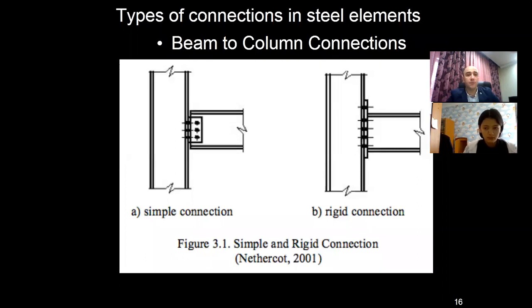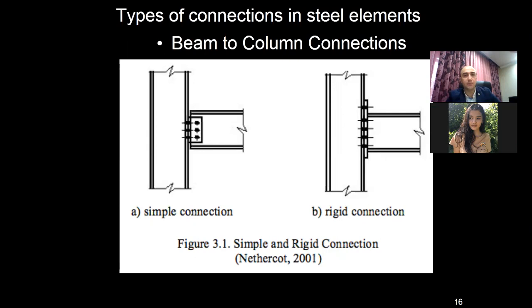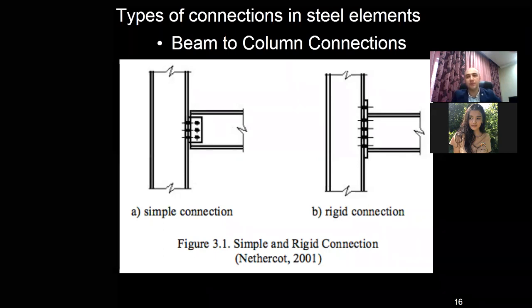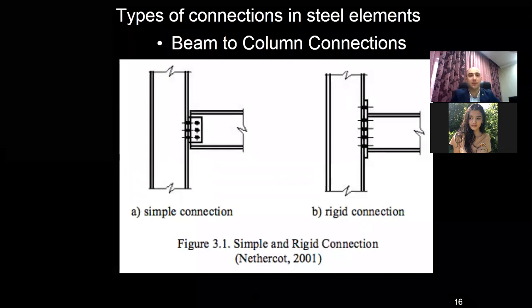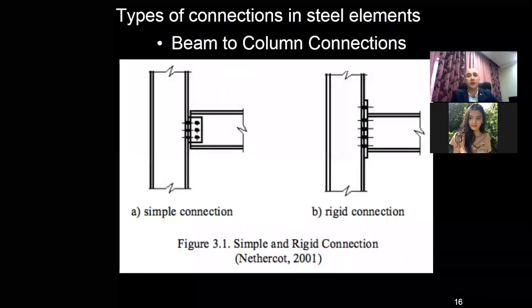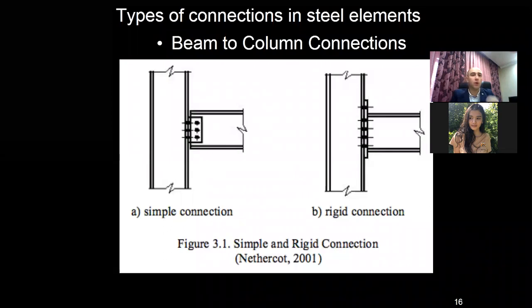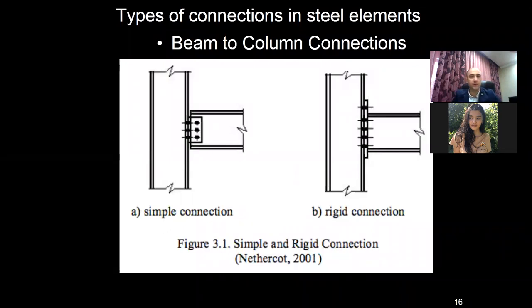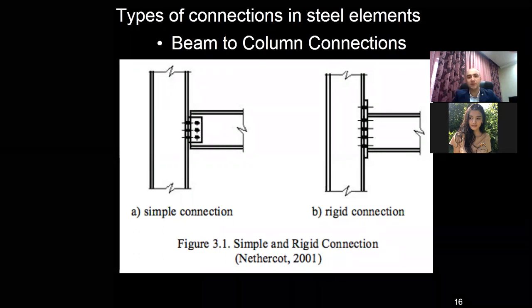Generally, a full strength beam to column connection is designed to ensure plastic hinge formation in the connection or in the beam, avoiding plastic deformations of the vertical columns. So all the components of the connection can influence the behavior.